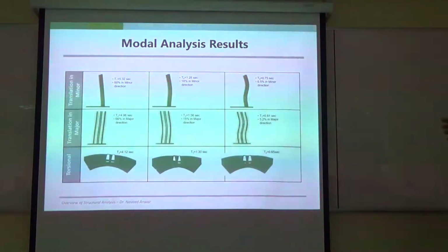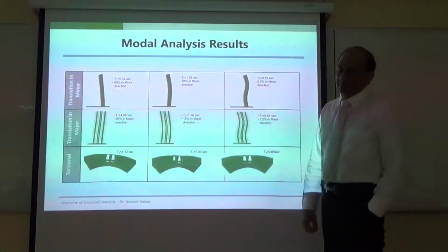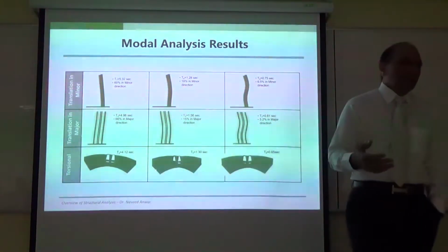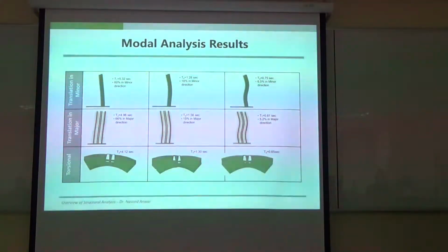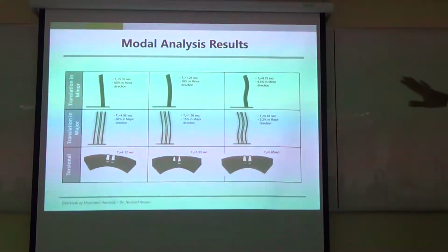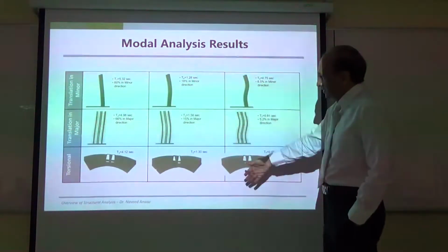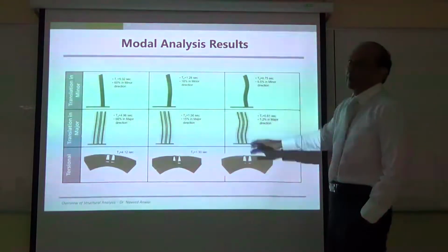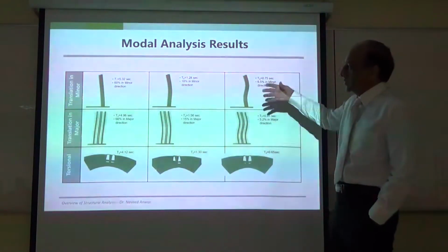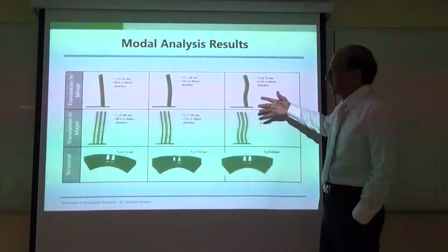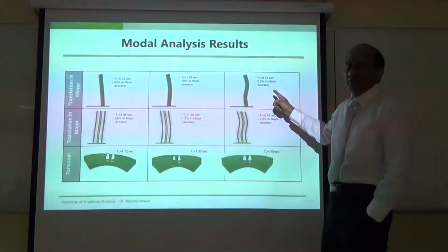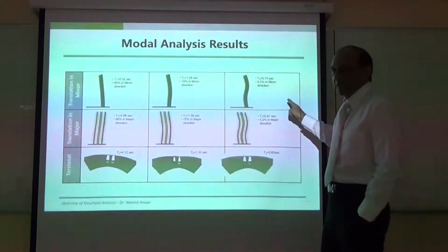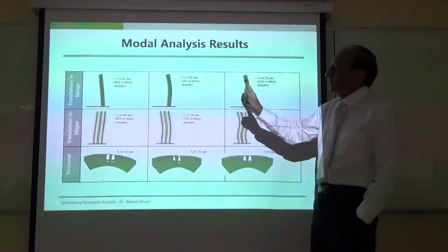Generally, this is how we look at the modes. And when you do the project, I'm going to ask you to plot your modes in the same way, in the same table. We'll give you a sample, we'll show you how to do that, but ultimately modes should be plotted, for tall buildings, in this matrix, like this. So translation modes in one direction, translation modes in another direction, and torsional modes. So first, second, third, weak direction mode; first, second, third, strong direction mode; first, second, third, torsional mode.